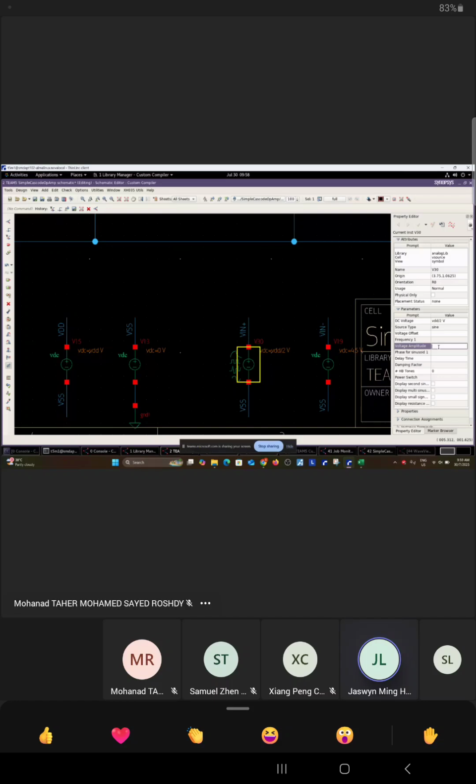So you will see that most likely, as the peak to peak input increases, the output peak to peak will increase as well, right? And then you reach a point where no matter how much more your peak to peak input increases, your peak to peak output will simply remain constant. That's where it gets clipped. So you know the operating region.